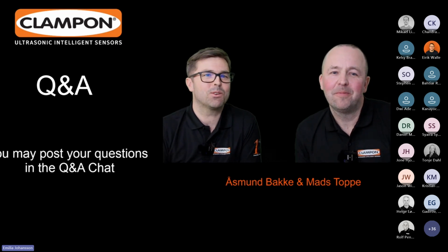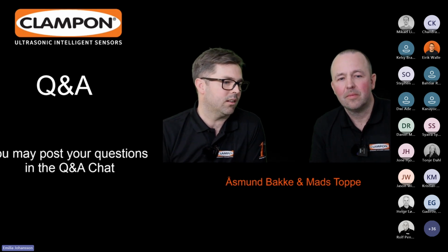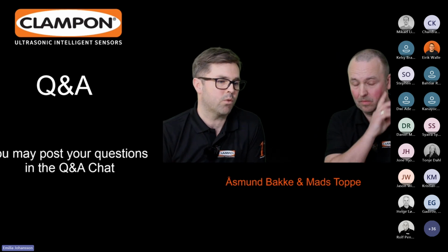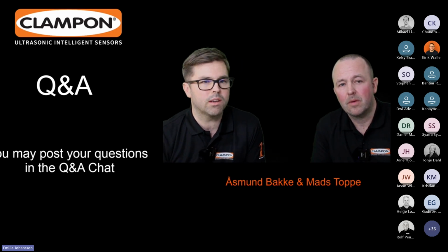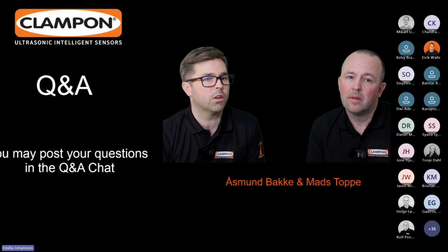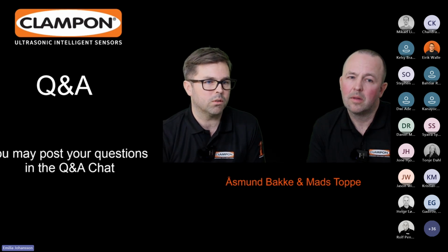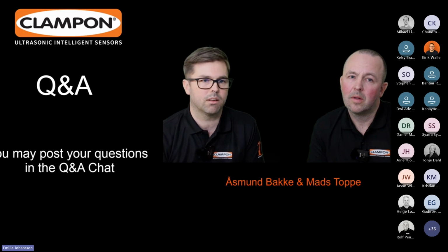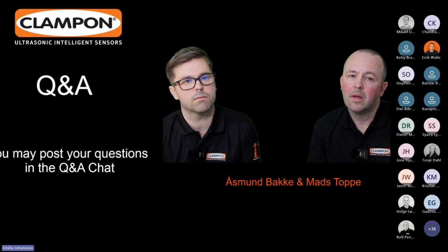So the question was if this software can do anything with unwanted noise, and the thing there is that the instrument itself, the ClampOn instrument itself, has a filtration, and that is not changed by this software. So the raw value we get from the instrument is the same, also with this software, but the auto zero and how we set that up can help us define more easily what's noise and what's sand. So indirectly, you can say that it will improve the sand rate calculation in noisy conditions.